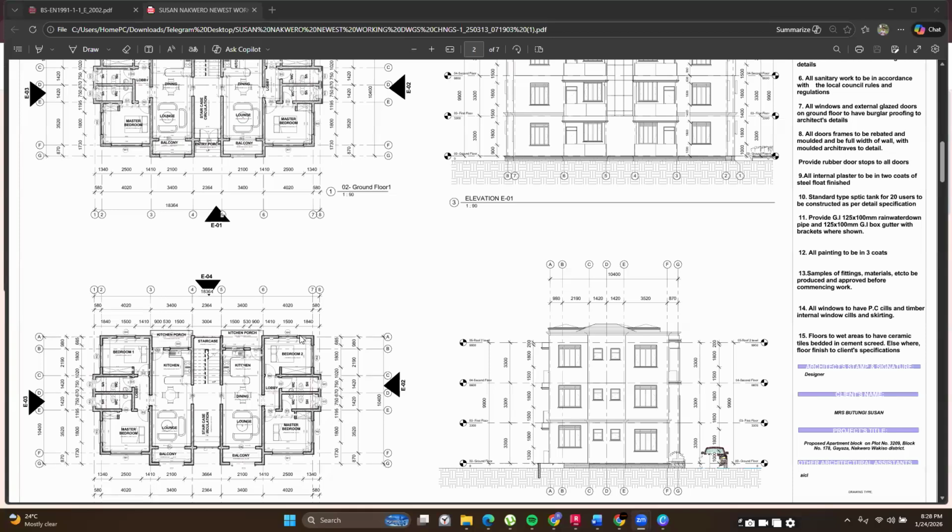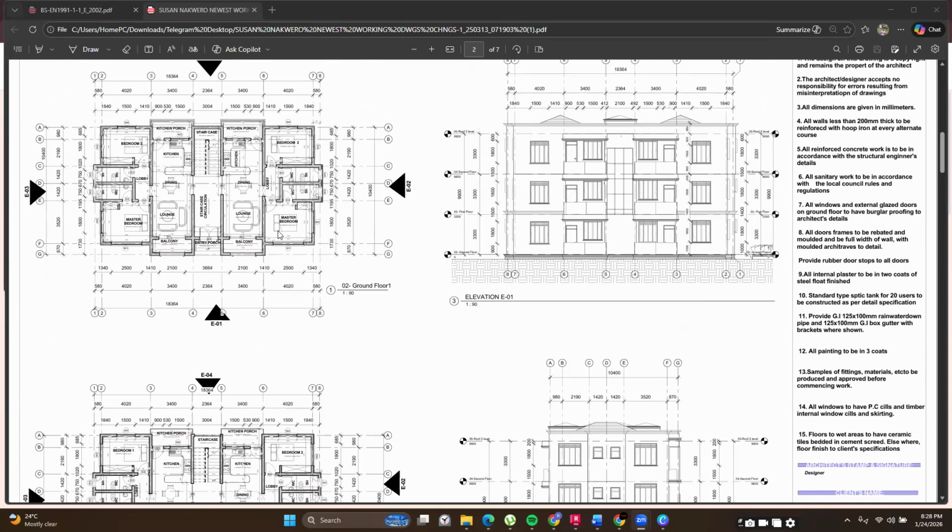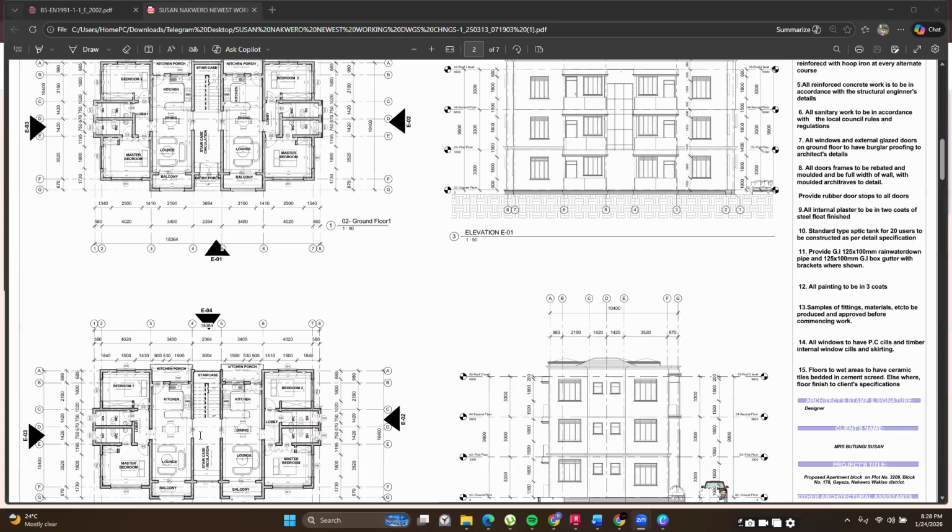Then as you place your columns, you can tell that when I place a column at this point and at this other point, they are not going to collide with the other architectural features or with the usage of the structure. You want to avoid scenarios where you have a column going through a room. Probably it's at a wall or a beam intersection in the lower floors, and then in the upper floors it is passing through the center of a room.